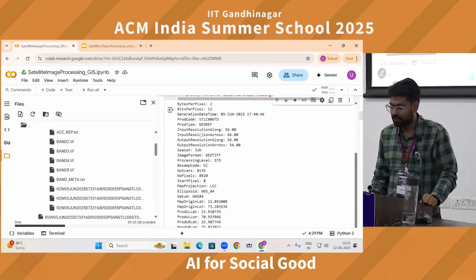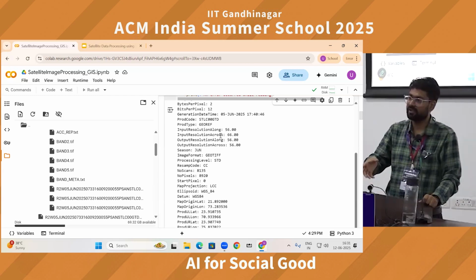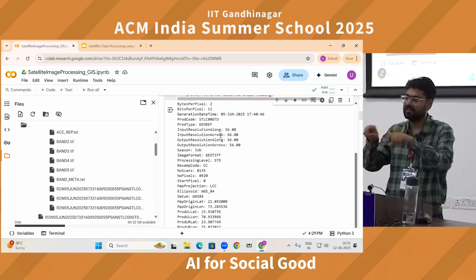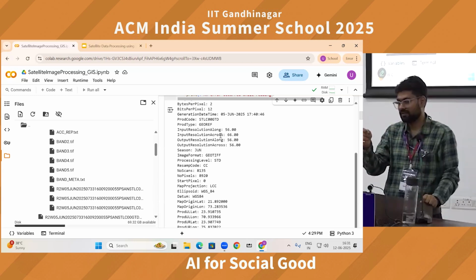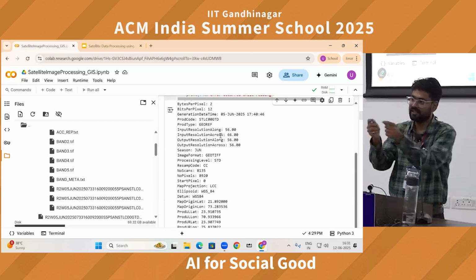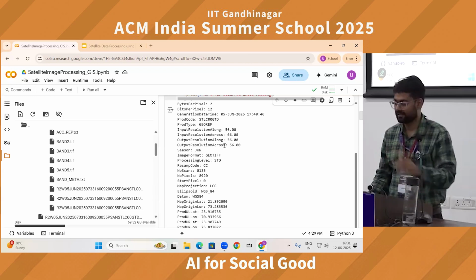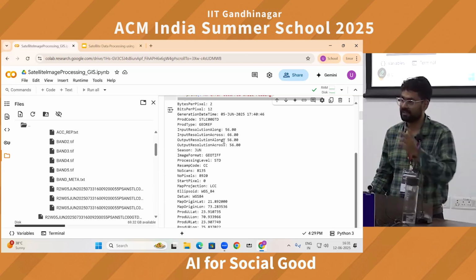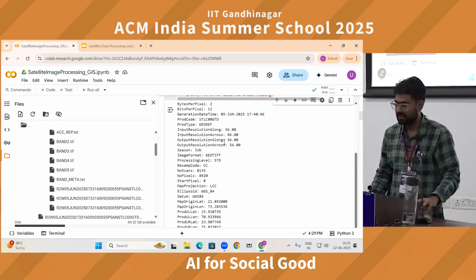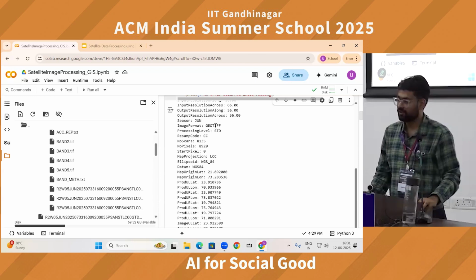Now, this is the input resolution, along and cross. Along means in the direction of the satellite. Across means in the 90-degree, the horizontal direction. If the satellite is moving this way, then the horizontal direction will be called the cross direction. The original resolution was 66, but for generating this product, we are resampling it to 56 meters. The image format is GeoTIFF.